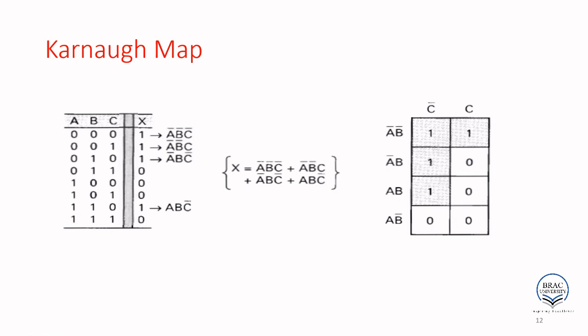So this is basically the three input K-map. You have three inputs, so 8 combinations. So you are given 0, 1, 2 is high and 6 is high. So just put them together, this 3 and this one. This is your X. So how can you draw it in the K-map? So this is the 3 input K-map. You have 4 columns, 2 rows, or you may have another way, 4 rows, 2 columns. Both are fine. So you can represent this as A prime B prime, A prime B, A B, A B prime, or 0 0, 0 1, 1 1, 1 0.